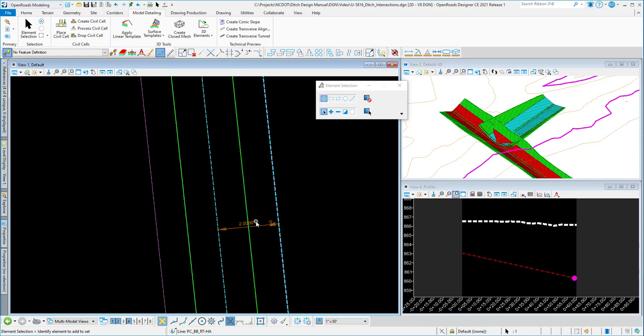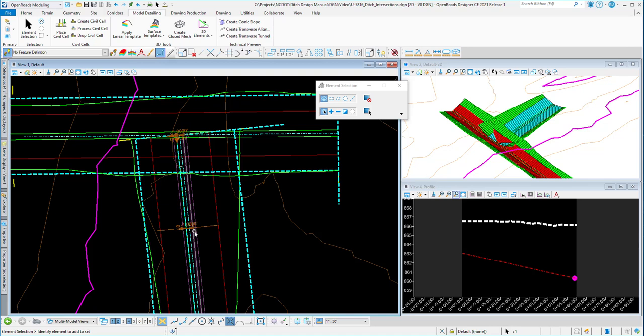They're set to an offset of 2 feet from either side of the center line. We need to change this to a 1-foot offset. So I'll change the 2 to a 1. Do the same for the other side. That's a left offset, so it needs to be changed from a -2 to a -1. And now that change is complete.